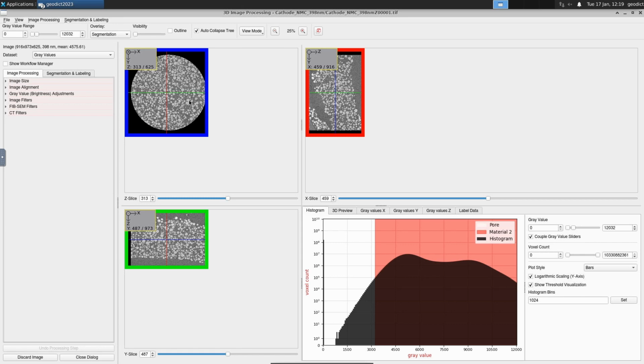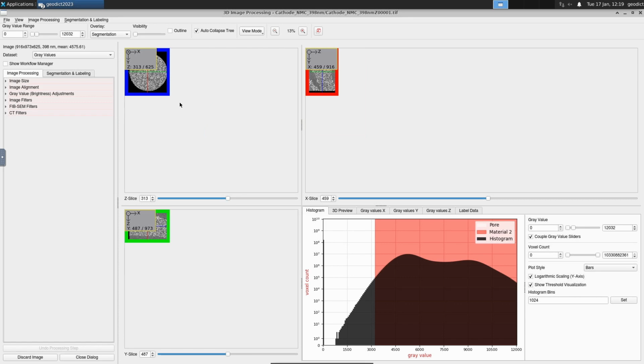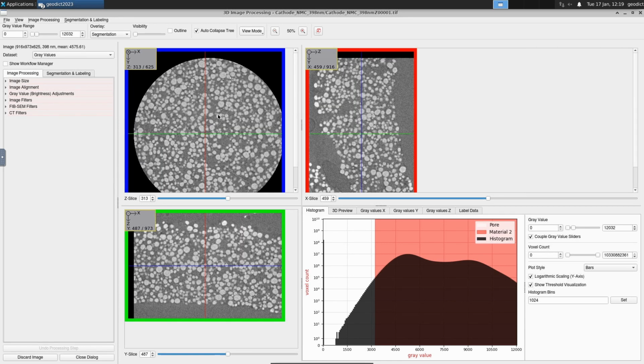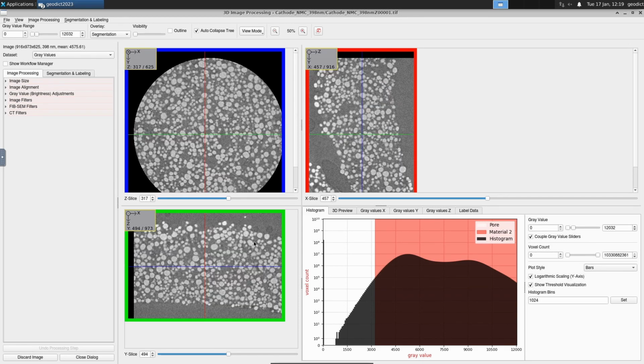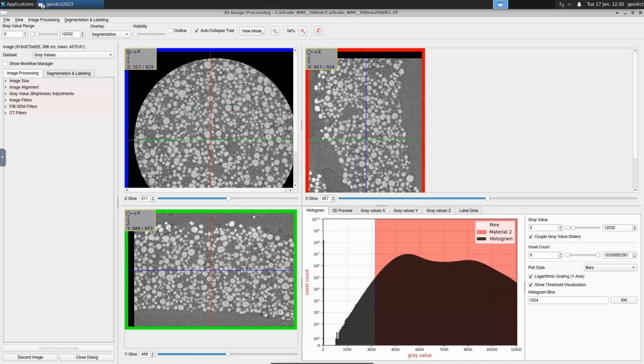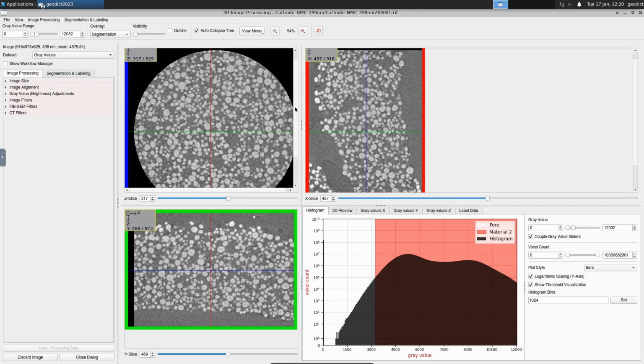You can zoom by holding the control key and scrolling the mouse wheel. So hold the control key and then you can stepwise zoom with the mouse wheel. With the mouse wheel alone, you can slice through the structure. So this works for all directions. And you can also zoom continuously by holding and dragging the right mouse button, as in the 3D view. So click and hold the right mouse button and zoom continuously. Additionally, you can also pan the structure with the sliders at the side here.